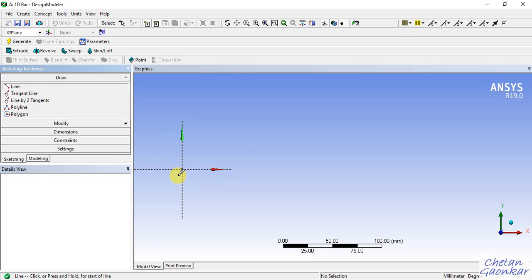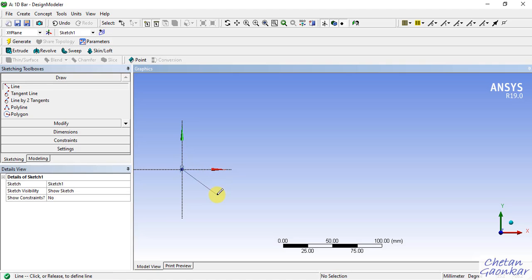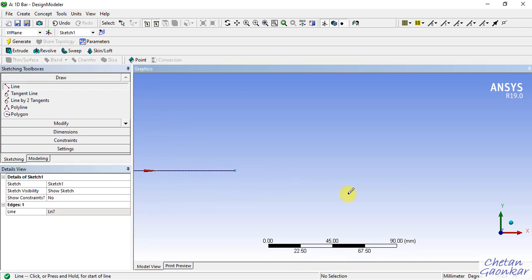So click on the line, you will see this P point, click there, and then just after clicking, now you can take this line anywhere, but I will align it in such a way that I get to see this H letter. Now this H stands for horizontal, which will tell us that once I see the H, if I click somewhere, it will give me a perfect horizontal line, and which is what we want, right? We want a perfect horizontal line.